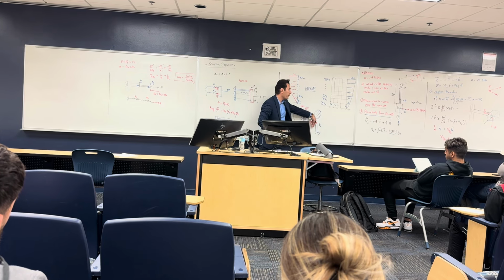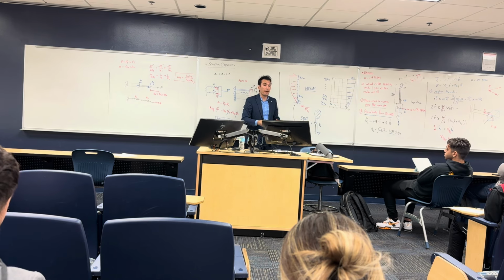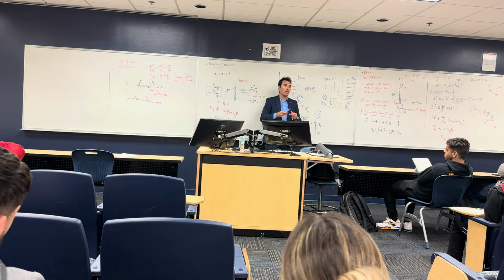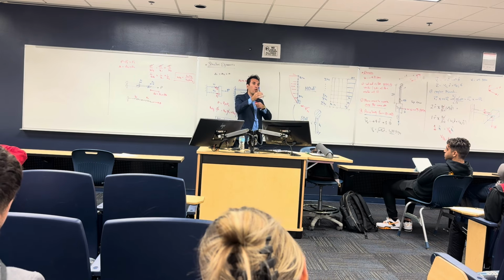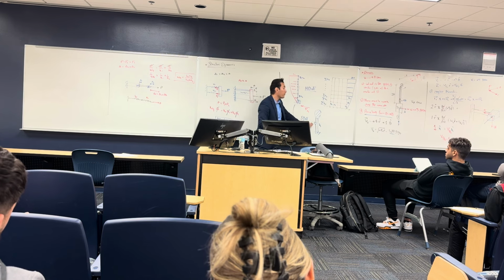Sometimes people neglect the damping and say we are going to solve a single degree of freedom undamped system, and sometimes people consider the damping. Sometimes we add damping to the structure, like we add what are called dampers. They put in a hydraulic arm, so when an earthquake hits, this arm keeps opening and closing to add more damping to the structure, so the damping is going to increase.